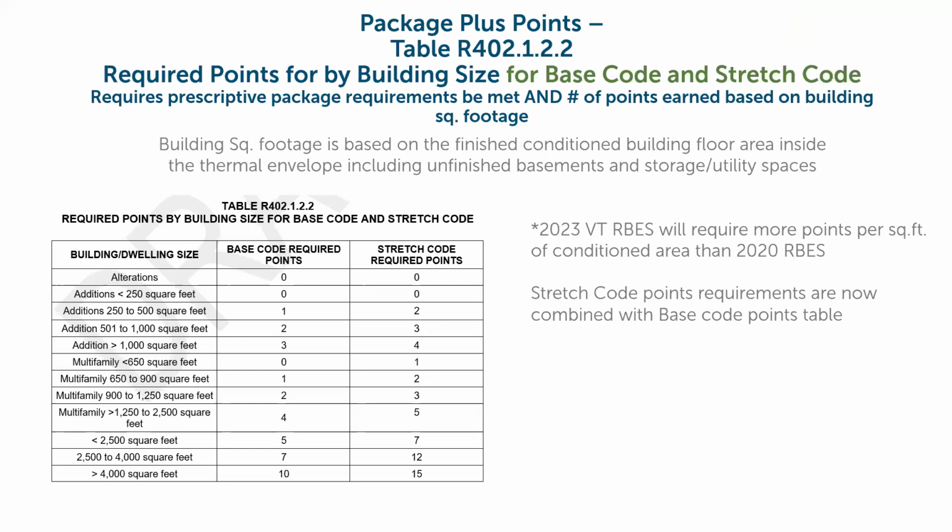Okay. So, when it comes to U values as well, it's a weighted value for all fenestration throughout the building too. So you technically could have some exposures or portions of the building that exceed that 0.27, but if that's balanced out by other units that are below that, then that's considered compliant as well. That's where more specifically the REScheck and the HERS rating option to show compliance allow for more flexibility with stuff like that.